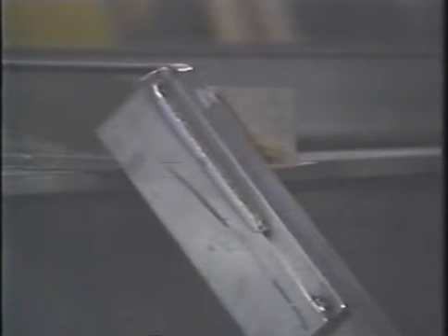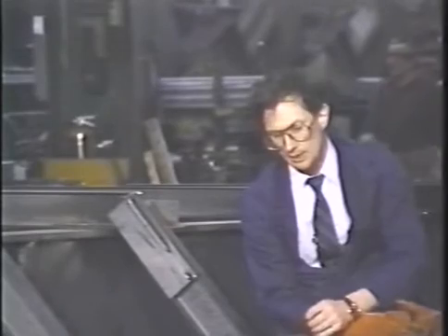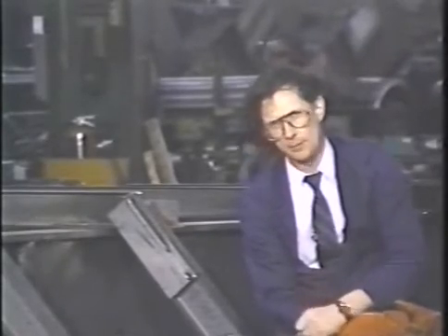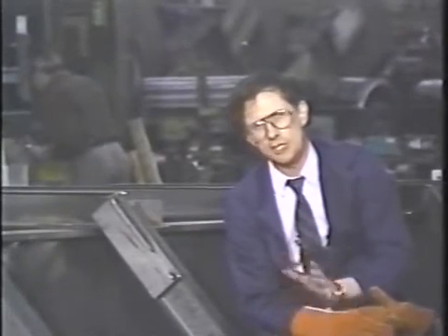When you select a welding gas for short-circuit welding, there are certain factors that need to be considered. If you're welding on very thin metals, less than, say, 60 thou, then it's wise to use an argon mix which doesn't have a lot of reactive gas in it.